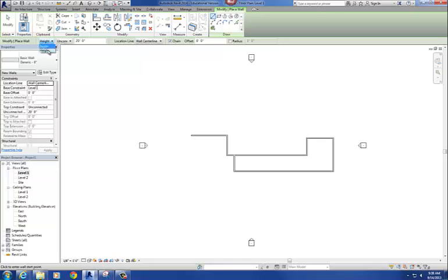You can either set the height or the depth. Obviously if you pick the height, then the wall's going to project up. If you pick the depth, then the wall's going to project down. 99.9% of the time, we're just going to pick the height. So I'm going to pick the height of the wall. And then where do you want to set that height? Well, that's what this next one here is. You've got a choice of unconnected, level 2, and level 1.